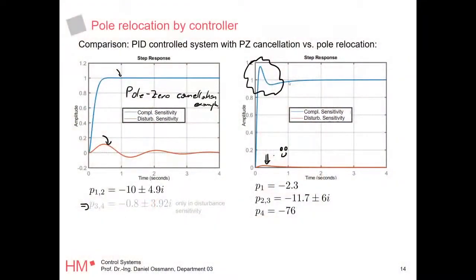You don't know the wind. Now you could say, okay, I can measure the wind. Yes, but these measurements are pretty bad and pretty expensive. You need a radar system, for example. They tried doing it with aircraft, but it's still not very feasible. You can, but it's expensive, it's heavy, everything you don't want as a customer. So bottom line is, we can still influence that signal because the system is excited by our pilot, by our user, so we can pre-modify it with a pre-filter, while we cannot change this one because it's a simple disturbance.